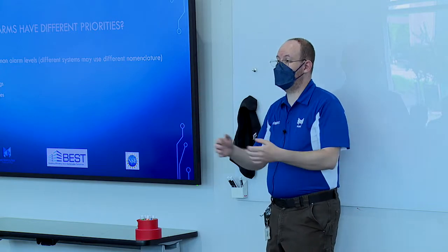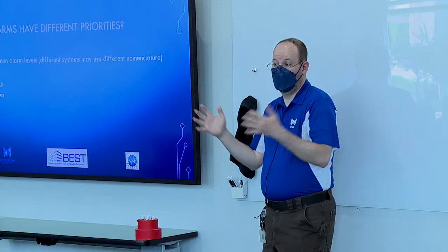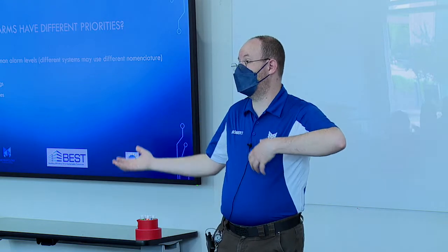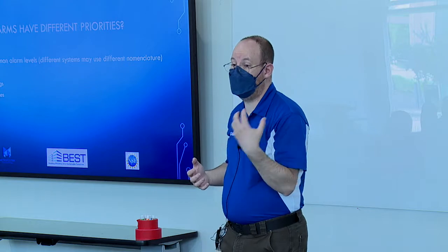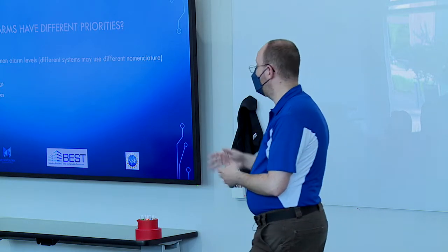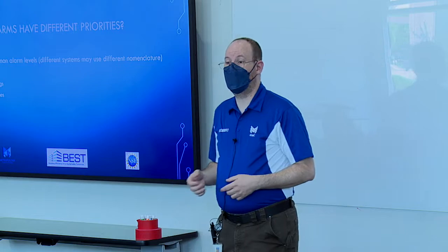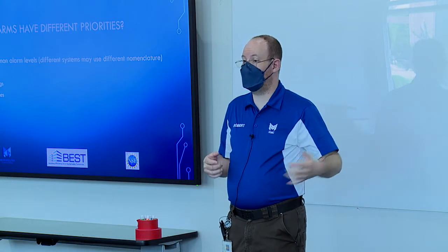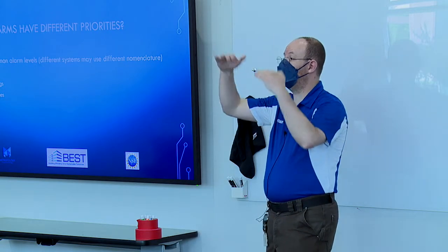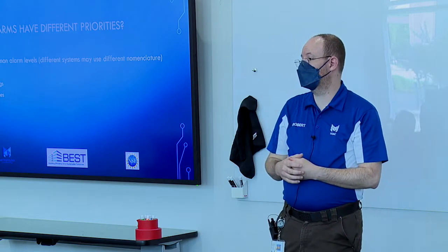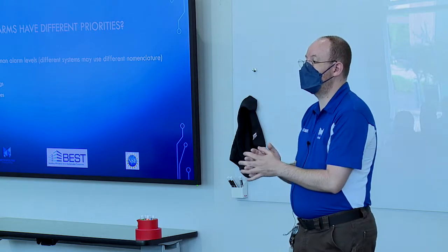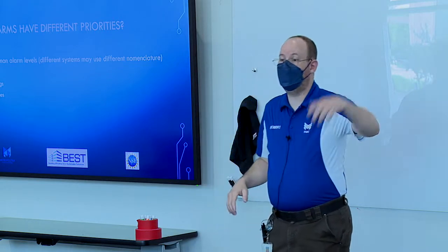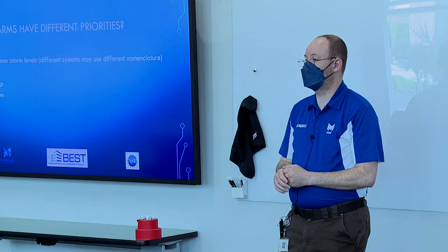Also, messages. Believe it or not, your building control system telling you general things that are going on can be a really helpful thing. Maybe your system will send you a message going into morning warm-up in the morning when that triggers, because you've got an optimized start-stop, so it's not always happening at the same time. But you can kind of track when it's doing and how it's doing. Or maybe it's going to send you a message, hey, it's been a month since you changed the filters.